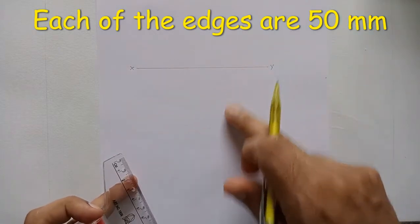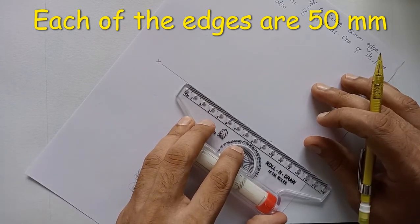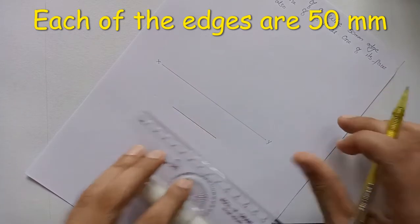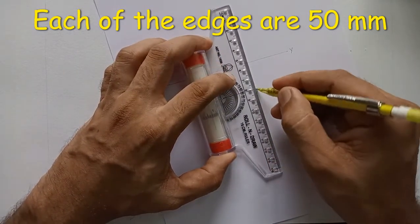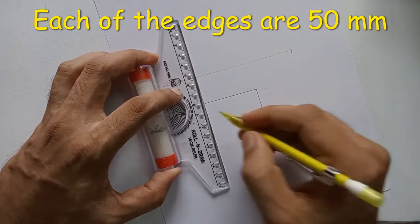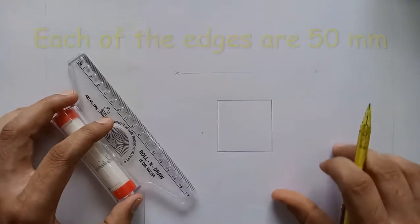Now we shall draw the top view of this square face of the cube. This is the xy line. Below the xy line we will obtain the top view. Take a line parallel to the xy line and draw a continuous thick line. This is the top view.